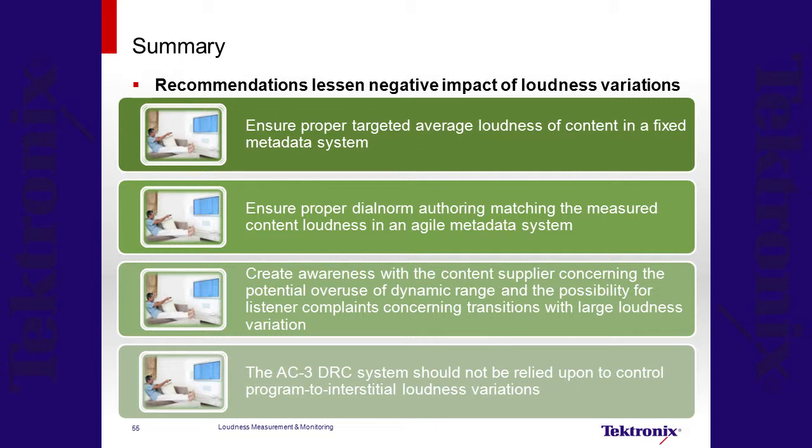It's important for broadcasters to create awareness with content suppliers concerning the overuse of dynamic range and the possibility of listener complaints when large loudness variations occur between programs. Additionally, the AC3 dynamic range control should not be relied on to control program loudness, and it's important that dialnorm is correctly maintained within the system for consistent dynamic range control in the home.